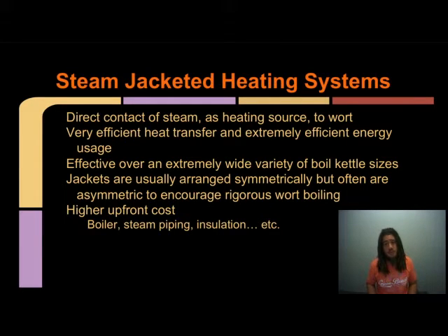Using natural gas is very good on low energy costs for a boiler. So over time, steam jackets and having a boiler is very efficient monetarily. The upfront cost is higher, but over time, the maintenance is pretty low, and it's not over the top as far as cost. You do save on your energy. Jackets are usually arranged symmetrically, but are often asymmetric to encourage a rigorous wort boil. So if you do have a kettle designed asymmetrically, your boil is going to go all over the place, bouncing off each other as the mixture moves with where the heat's coming from.